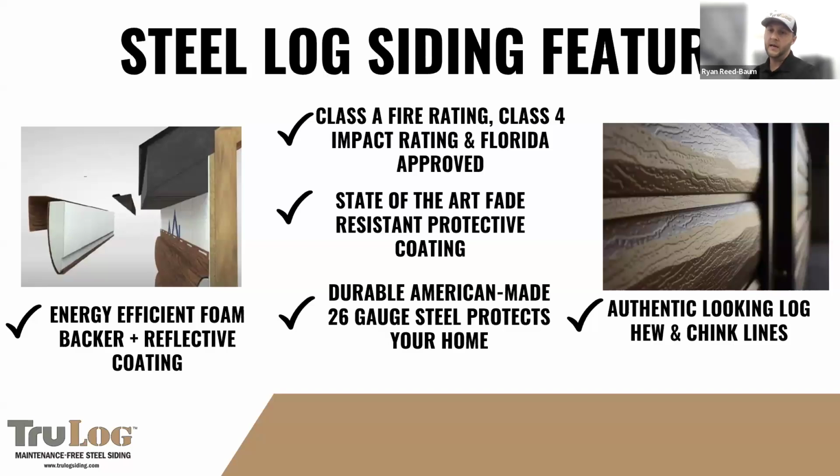Specifically, and this kind of goes across all of our steel siding products, we went out and had a bunch of testing done. So we have a Class A fire rating, we have a Class 4 impact rating, and we also just recently got Florida product approved. And we are working on getting WUI approved, which is the Wildland Urban Interface, which is a little bit more of a step up from the Class A fire rating. But that's across all of our different products that we have tested.